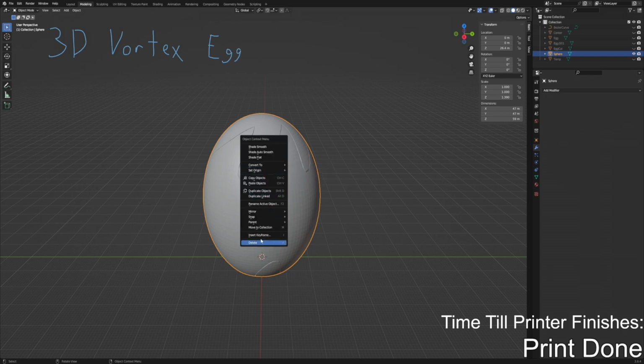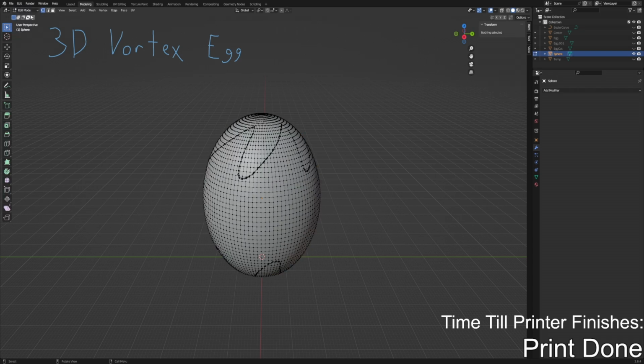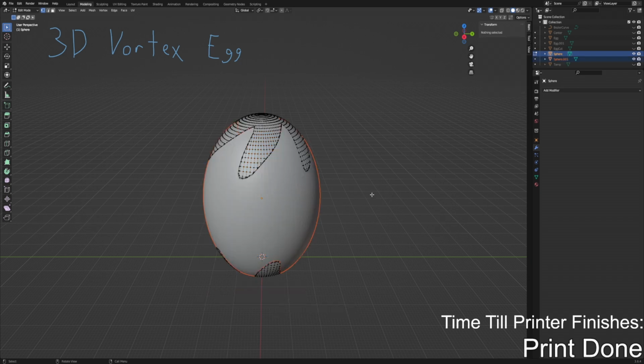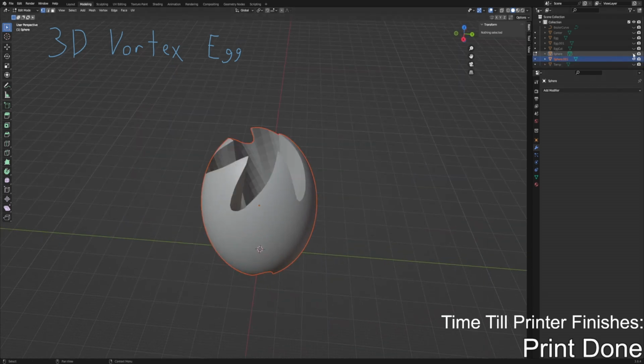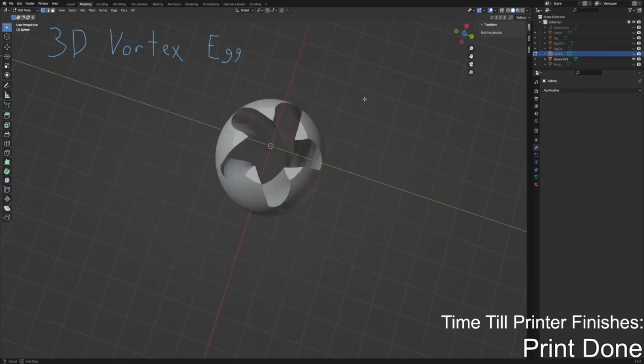And then I can just go up here, right click this in edit mode. Select all. And then you want to separate, which you can hit P apparently, and separate it by loose parts. So now I have two objects. I have sphere and sphere 1. And imagine this. I hide sphere, and that's the inside part.